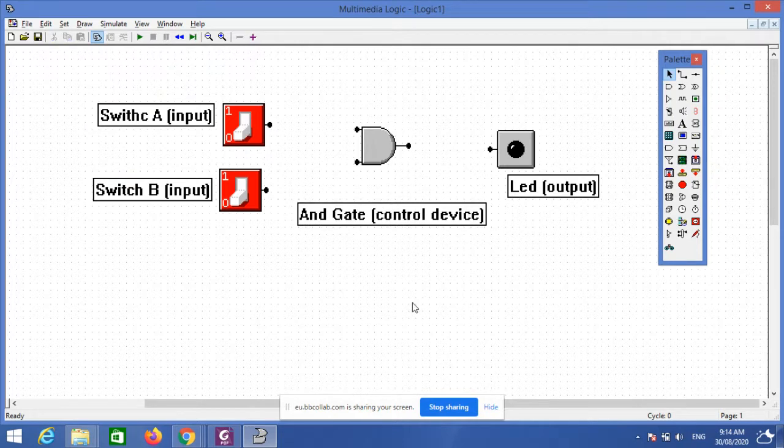Now, how will you give connections? These are the components. We have to give connections with the help of wire. So you click on this wire. Then you see the black spot. Take this plus center here, click the mouse and don't leave the mouse button, drag like this and connect like this. Then leave the mouse button. Then it creates a link. Similarly, click here and don't leave the mouse button, then leave now. It will create a connection. Similarly, you have to make all the connections.